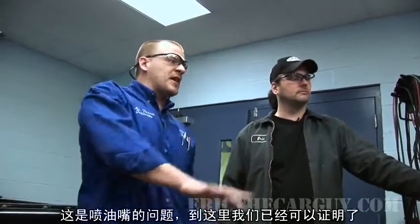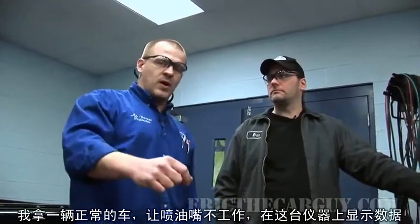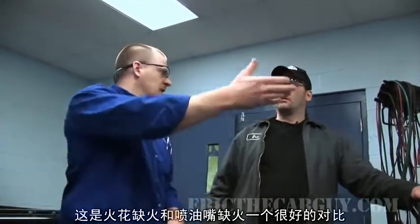And we'll prove it as we go here, but I showed you guys this. Remember, I shot the video and I didn't upload this one yet. I need to. What I did is I took a known good car and I disabled the injector and showed this machine and we got our numbers, and then I plugged that back in and disabled spark and we had our numbers, and it was a real good comparison for an ignition misfire and the type of levels you have compared to a fuel injector misfire and the levels we have.